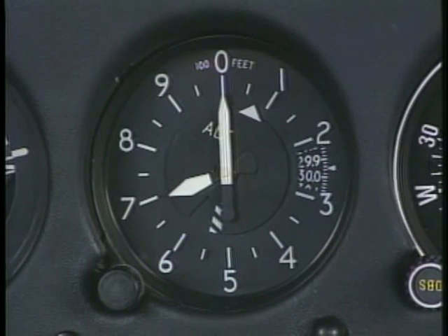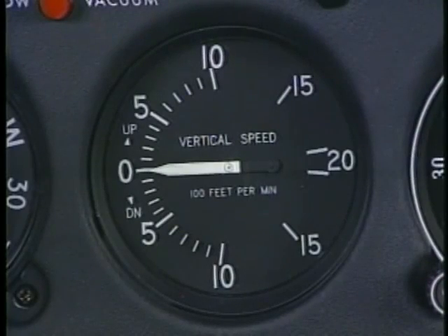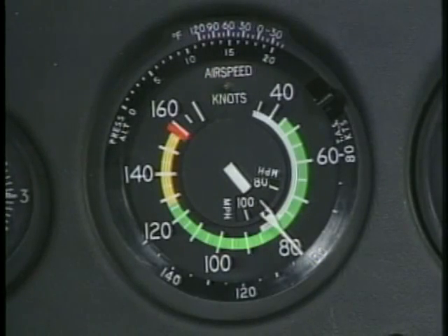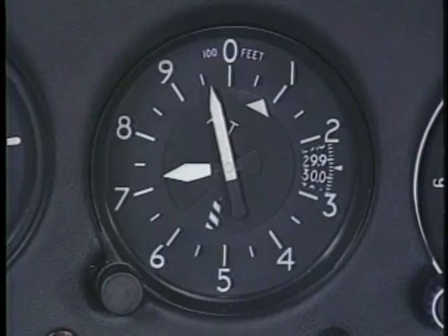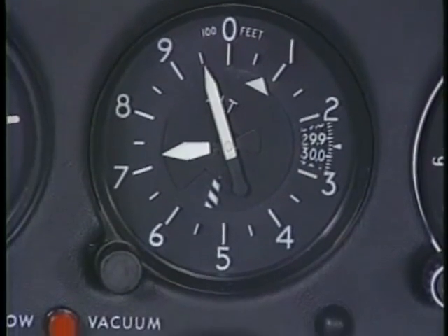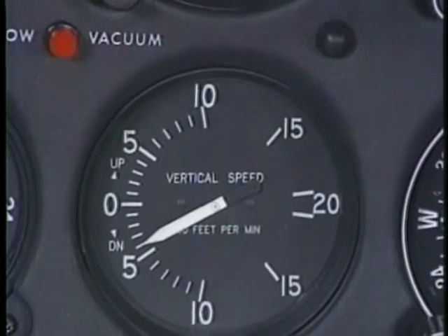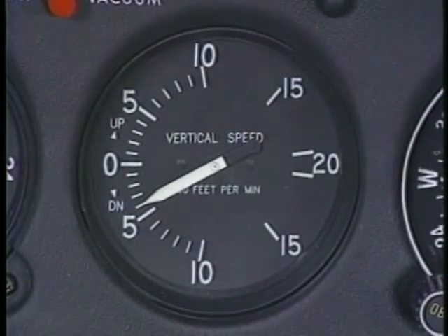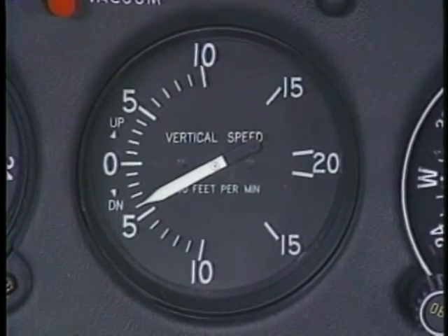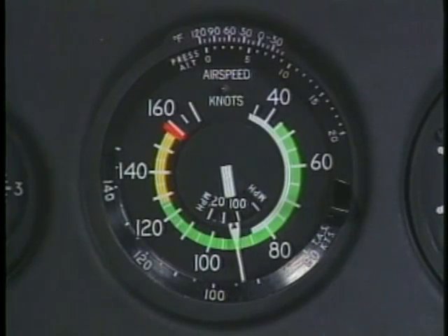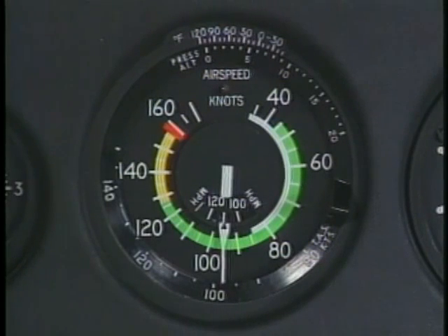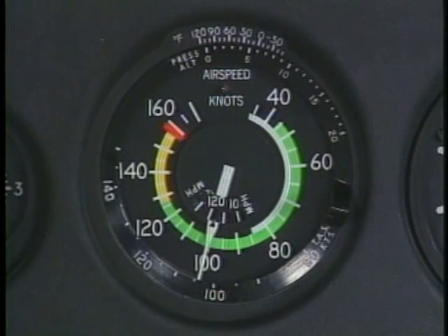After the correct attitude has been established, confirm level flight by referring to the altimeter, vertical speed indicator, and airspeed indicator. If your altitude starts to change, look at the VSI to determine the rate of the change. A small rate change will only require a minor correction. You should also check the airspeed indicator to see how the pitch change has affected the airspeed. If the airspeed is extremely fast or slow, you'll have to make a larger correction.